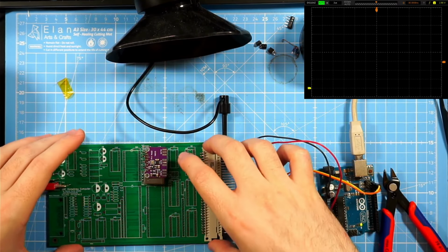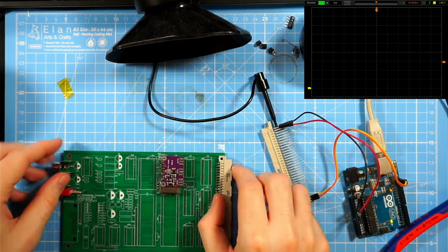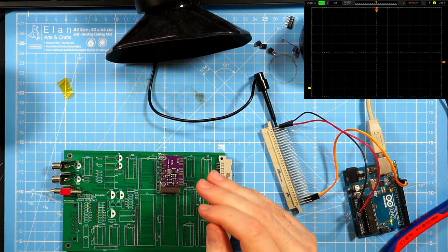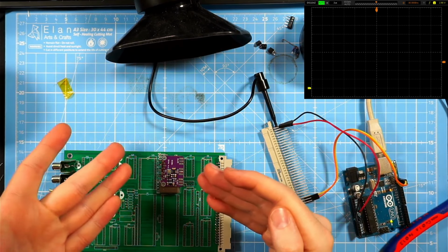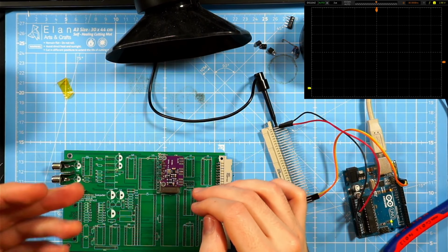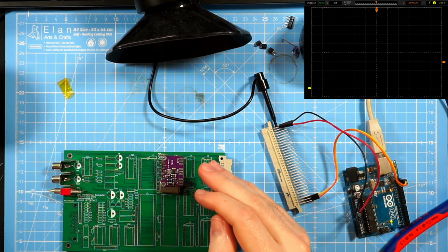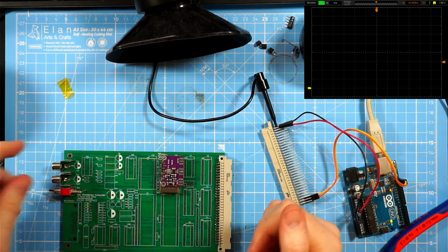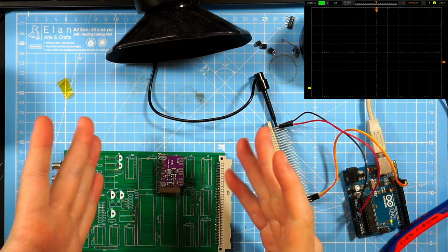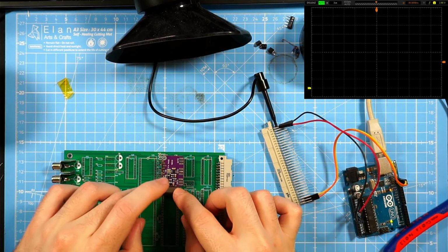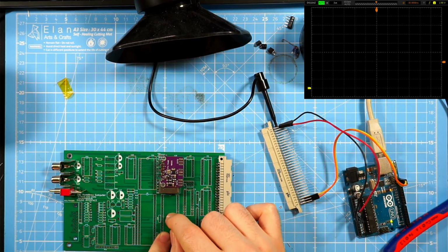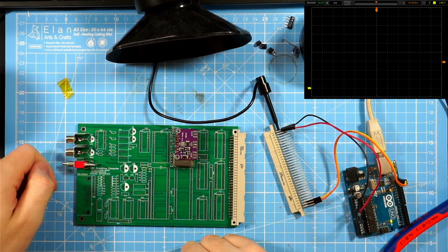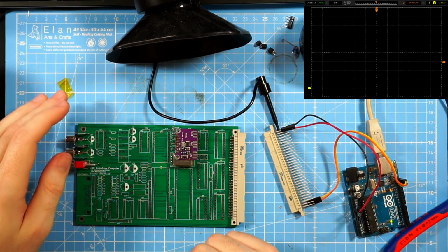Now it fits. Perfect. It turns out that sometimes the solution is much simpler than you think it is. By just bypassing those level shifter transistors that I thought would be a good idea, we get the clock signals at the corresponding pins. The clock generator for the SIO that serves the MIDI ports is working. So the only thing left is to populate the rest of the board, and I'll show you a small time lapse.